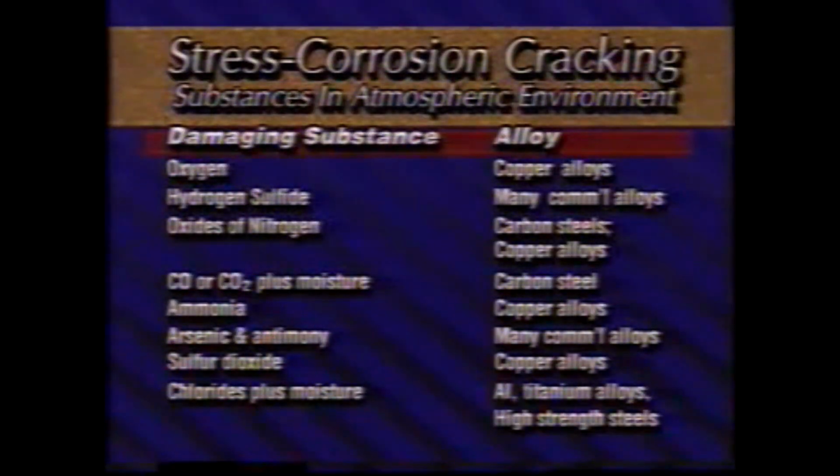Stress corrosion cracking frequently occurs in commercial grades of low carbon steels, high strength steels, austenitic stainless steels, and other austenitic alloys, high strength aluminum alloys, brasses, and certain other copper alloys. High purity metals generally are much less susceptible to stress corrosion cracking. However, every metal will stress corrosion crack in at least one environment.